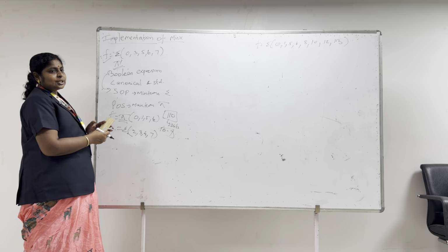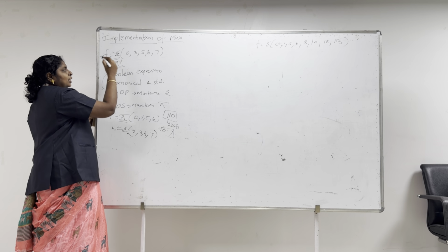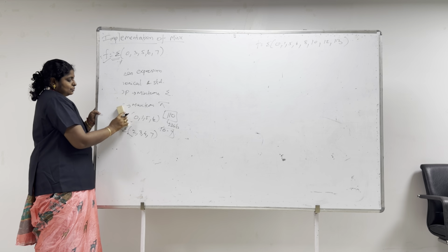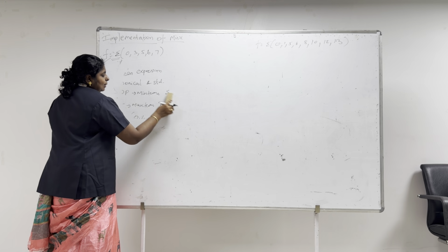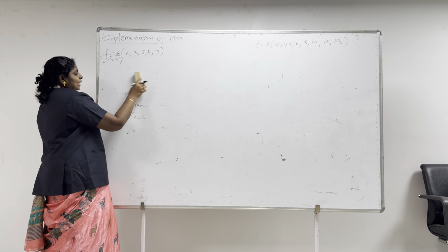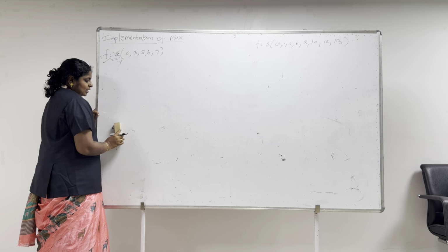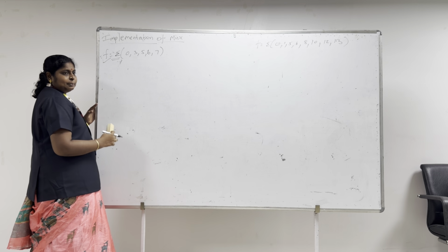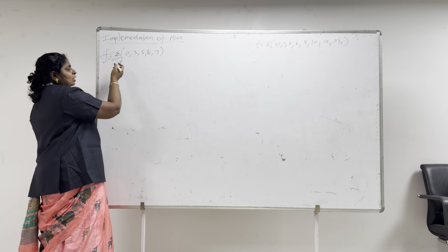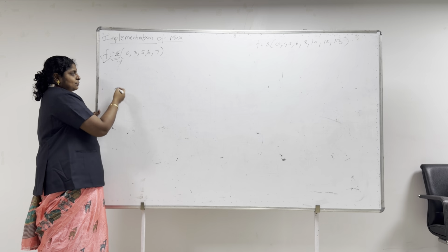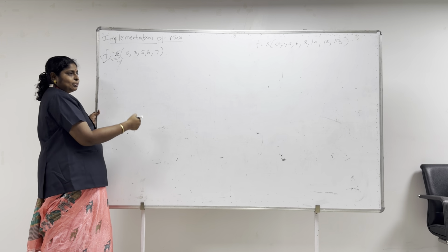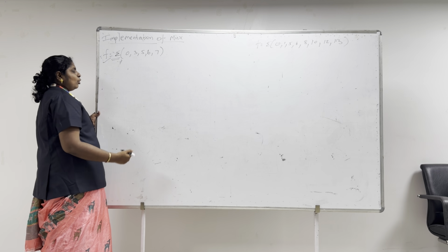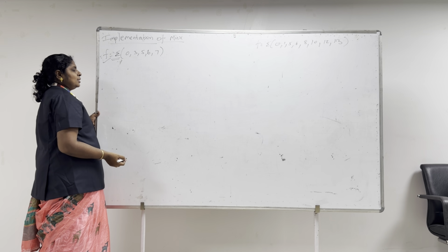This mux implementation should be done with the correspondence of the min terms. So with these min terms we proceed with the implementation of the mux. Your mux structure can be built for whatever Boolean expression is given. The Boolean expression will be given as the application. Based on whatever application is given, from the logic the truth table can be framed, and from the truth table these min terms can be obtained. So these min terms can be implemented in the mux.